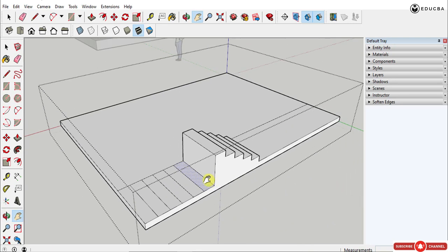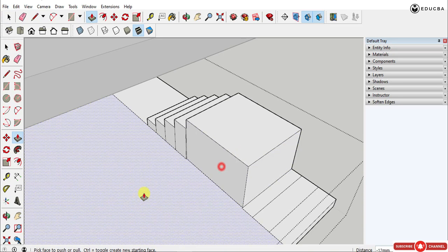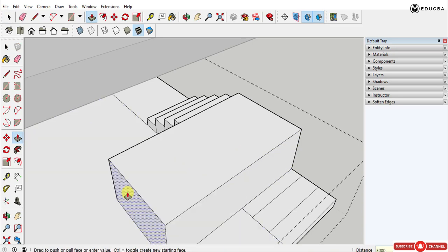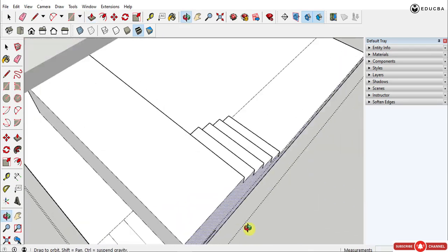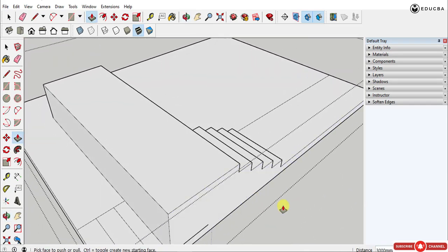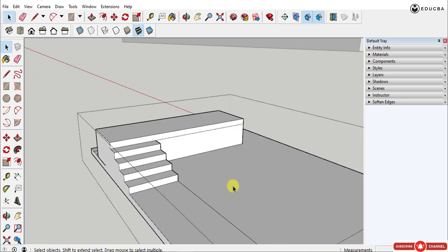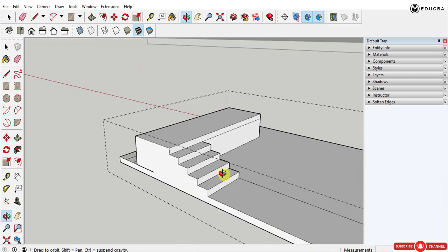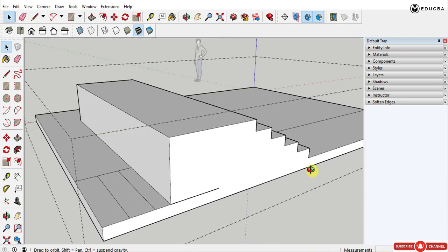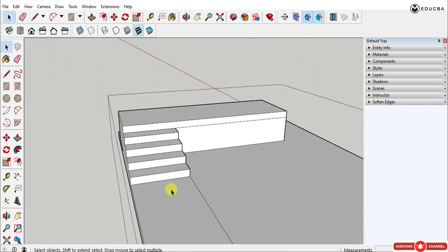After this, you need to create a mid landing, say 1000 mm. And again continue the same procedure by pulling this surface by another 3000 mm, or approximately whatever is the distance that you are going to require for your dogleg staircase. In this particular instance, it is a tedious procedure. So instead, we are going to learn how to use plugins which can create these entities or such models or such small detailings whenever required.